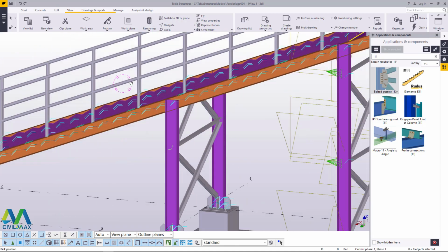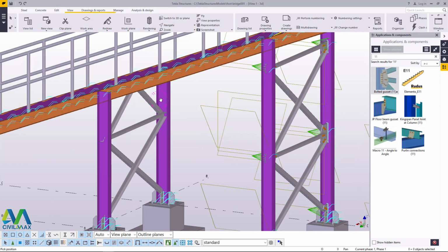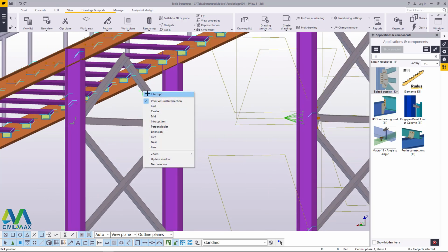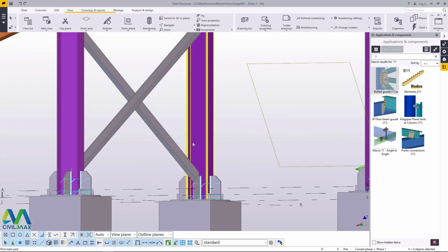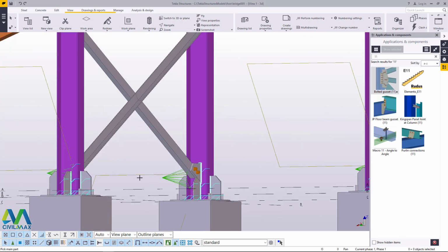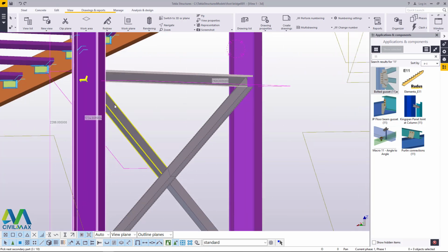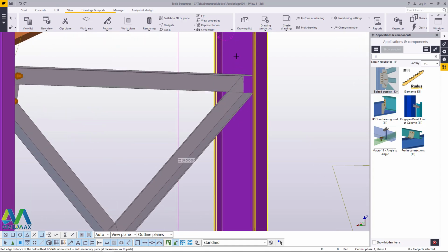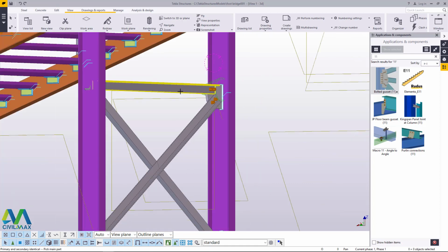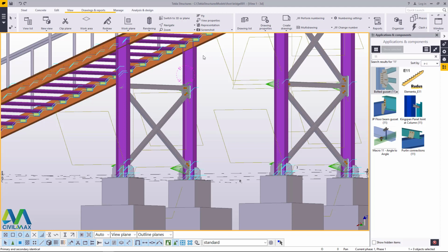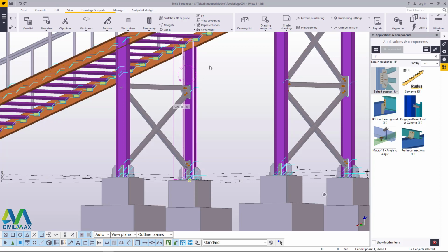Now to our last trestle here. Let's check the braces. First of all, get rid of this because it serves no purpose here. Get rid of it and just create our connection here, here, and here, and we connect this and that. Press the middle button and the connection is not well placed. We can fix that. Connect this and that. That has been created. Then we right click and redraw everything to remove any unwanted symbols on our connections.